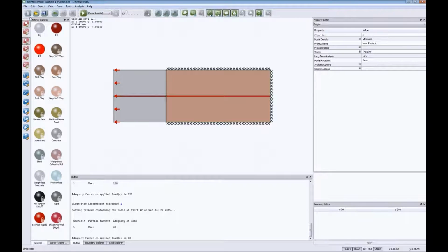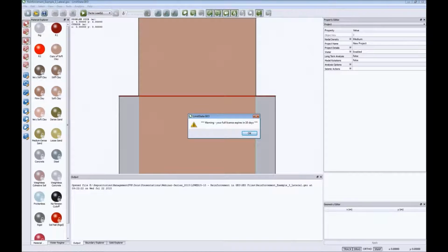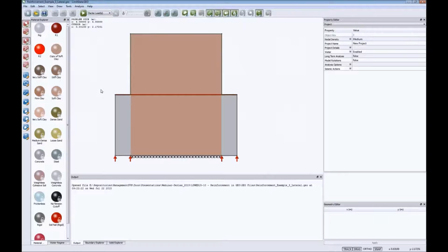If I model, just show some lateral effects. Now, generally with reinforcement, we model only tensile interaction and shear interaction, and generally ignore the lateral capacity. But if we have a soil nail or indeed a pile and we wish to look at its lateral capacity, piles obviously we consider their lateral capacity, trying to move a pile sideways through soil. Equally well, if soil is moving normal to a soil nail, we'd expect a little bit of resistance. Though typically that is ignored in conventional analysis.